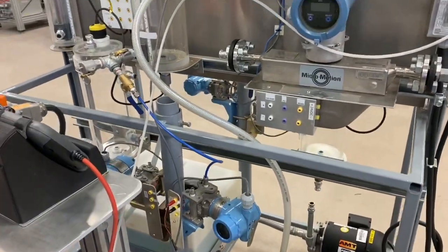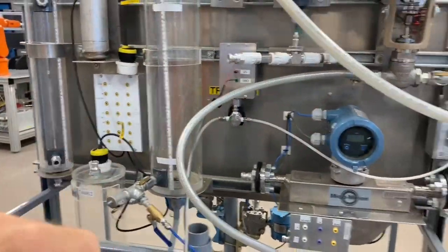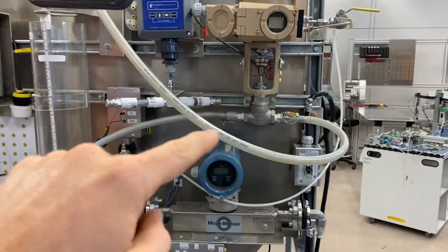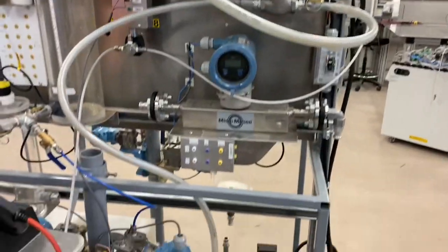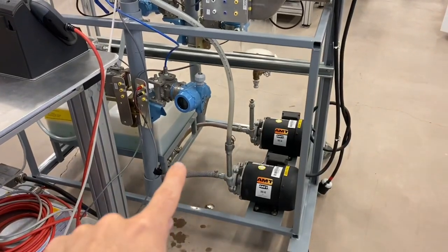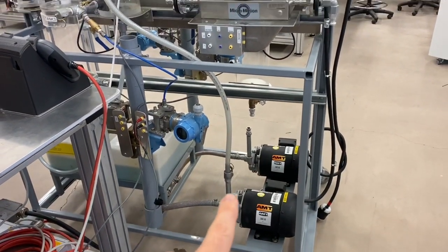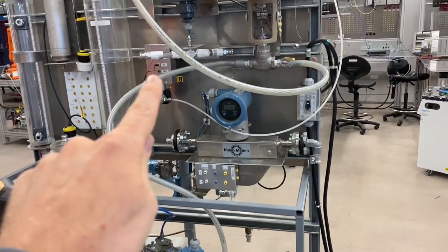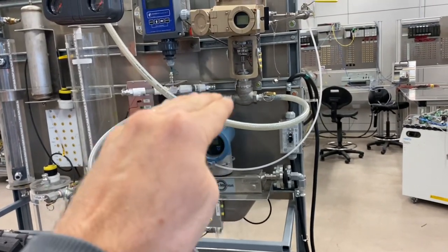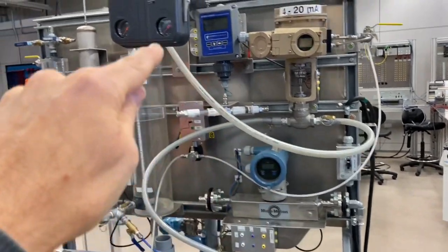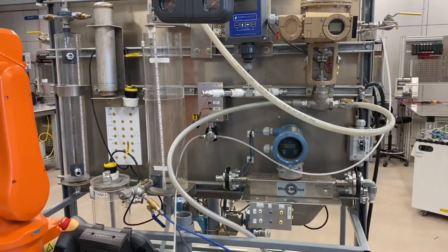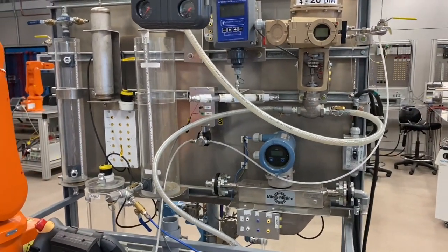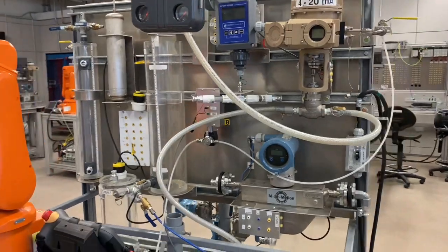So we're measuring the level here with an analog input, and we're controlling the level with this solenoid that then controls this valve over here. If we back out a little bit more, you can see off the bottom, we're sucking water through this pump, and it goes up to this valve, which we control with the solenoid, open and close, and then into the vessel. So in this lab, we're going to be writing a program to control the level in that vessel. Let's go back over here and look at the wiring.